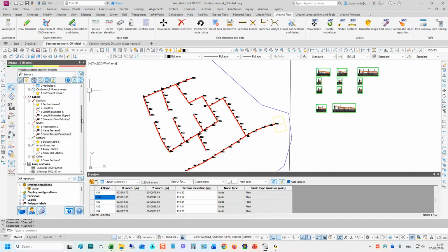You can import the data basically in the most basic way. You can import it from text files, but you can also import it from shape files, which is very important when you have proper GIS systems and you want to use them. You can import the data from databases. You can import from, let's say, Land XML, from Civil 3D, from INP files, both for water and network, and so on. And you can also export networks in all those formats, but also you can export it to IFC and NVC that I also mentioned at the beginning.